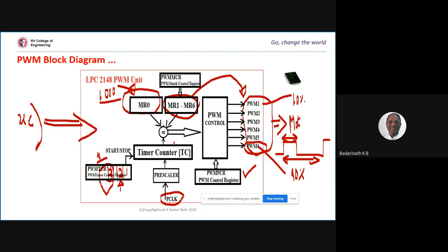There's one concept available here in the case of a PWM module. It is called shadow registers. What is the concept of shadow registers? Let's say the motor is running at a particular speed, say 500 RPM. In between, you receive an instruction from the user to change the motor speed to 300 RPM. The PWM waveform is going on and still not completed; it is in between one clock cycle. Somewhere the programmer wants to instruct here because he wants to change the speed. You should complete the cycle and only then start the next one.